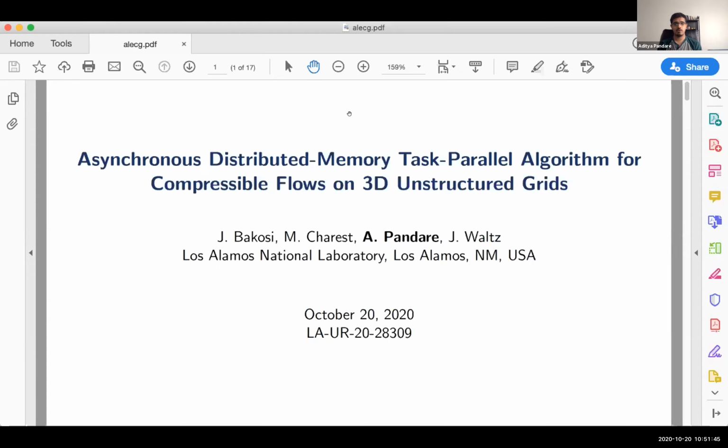That's one of the very important things here, because as compared to internal flows, these external flows require meshes which are a large magnitude larger than the internal flow meshes. So you would have 3 or 4 orders of magnitude differences in these meshes. So we would routinely see meshes such as tens of millions or even a billion cell large meshes. That is why we would like to have an extensive parallel capability in the code.